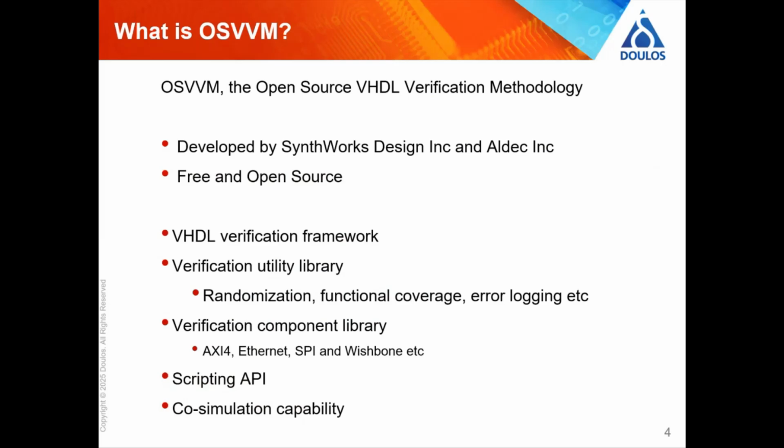So traditionally, I said traditionally a lot today, but the way that this has been solved has often been through SystemVerilog and maybe UVM layered on top of that. But it's not the only way to solve it. And certainly for VHDL-based houses, it's not always a path that they want to go down, because it's a whole new language, and it's not a little language either. SystemVerilog is massive, and UVM is massive on top of it.